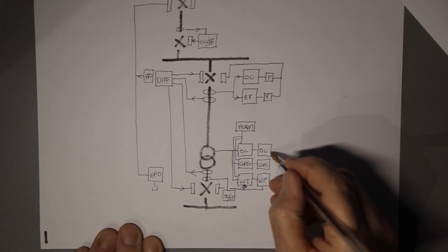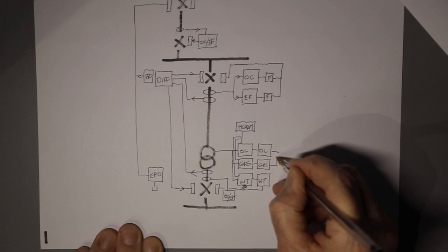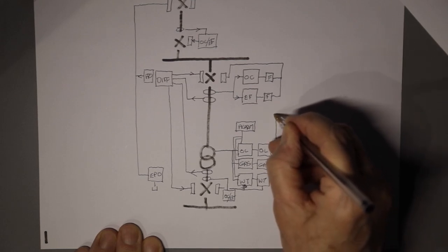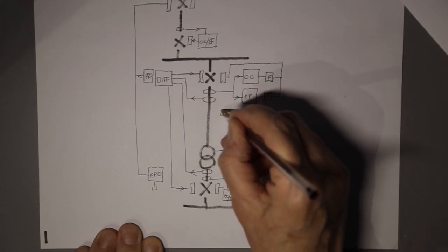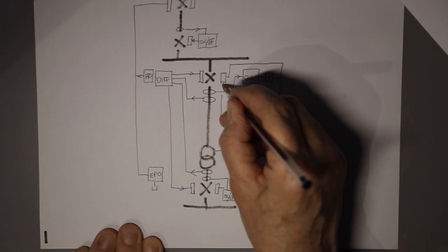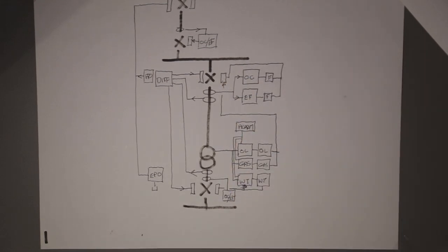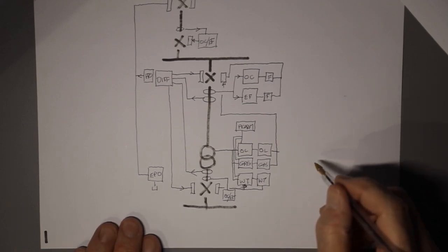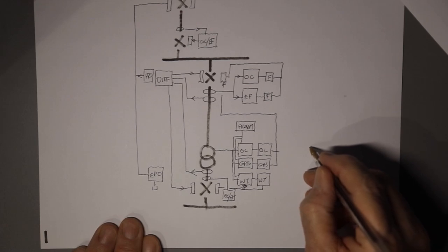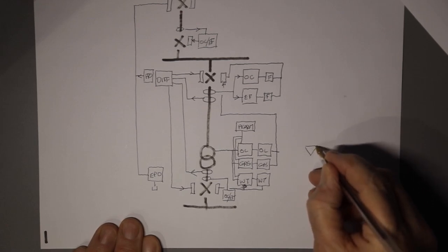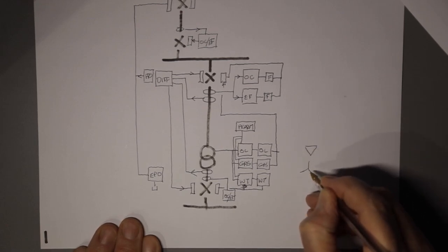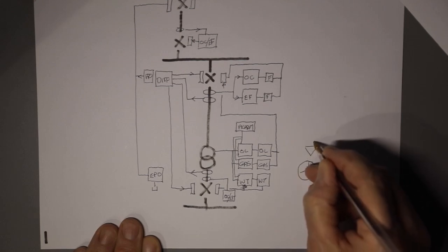So what I'm trying to show here is that I've got an alarm, but I haven't got anything to trip. So now I'm drawing a not very neat line. If this was AutoCAD, you'd lay out everything, but it shows quite clearly that a low oil, not an overload, a low oil and a gas alarm would operate the shunt trip coil on the main circuit breaker.